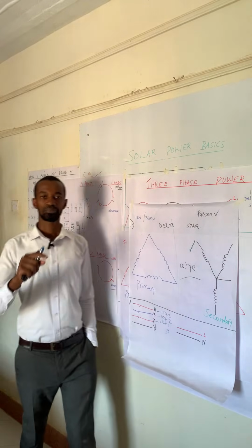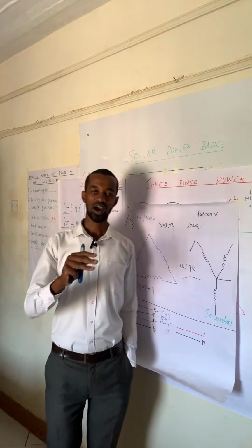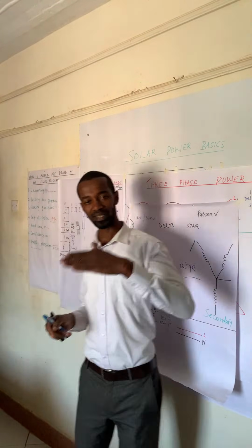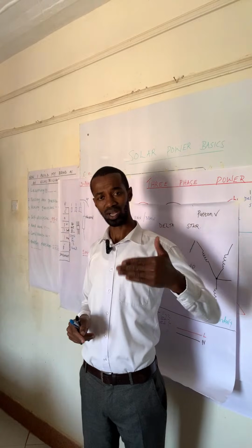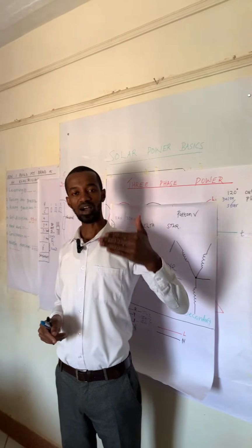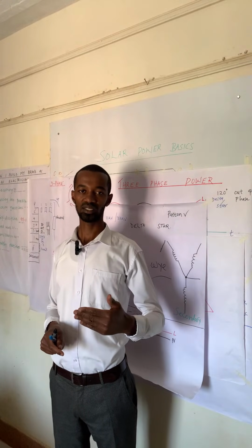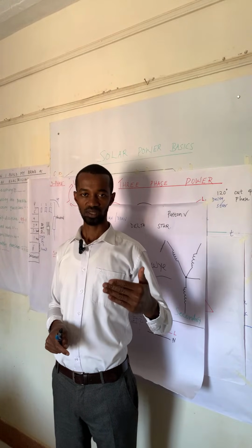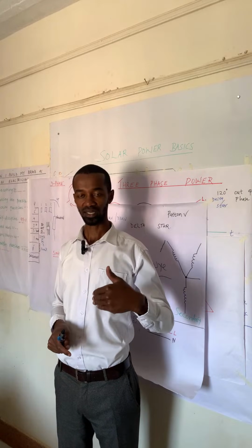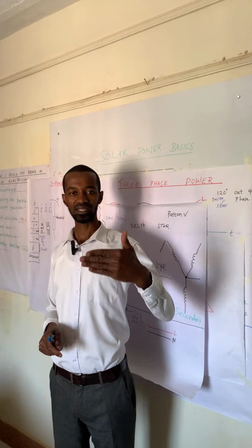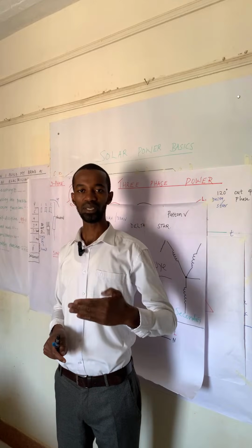In industries, in places where you have a surge, which is especially internal, this occurs simply because you have a neutral that is broken, therefore resulting in an internal surge. And that surge can lead to a rise in voltages, which can damage appliances.